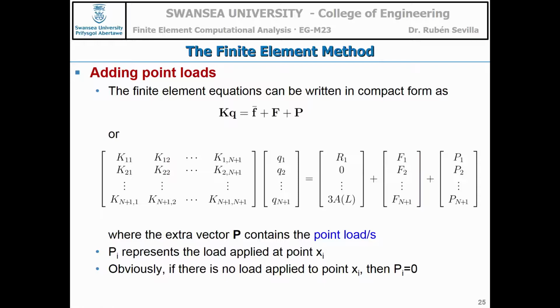If you know a Dirichlet boundary condition, what you have is a reaction there. And if you know the traction, you put it there in this vector. Capital F accounts for external forces. I'm just splitting the right-hand side to understand it a bit better. It's a contribution from the boundary, the small f I call it, and a contribution from the external forces, I call it capital F.